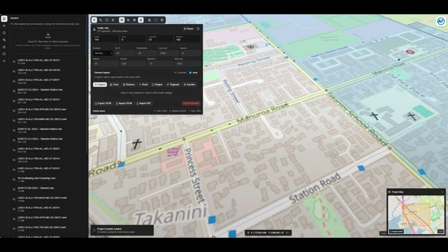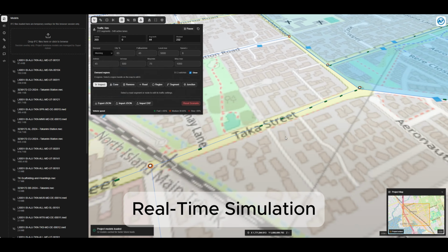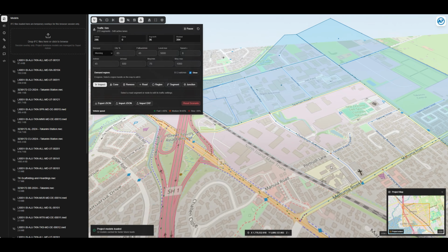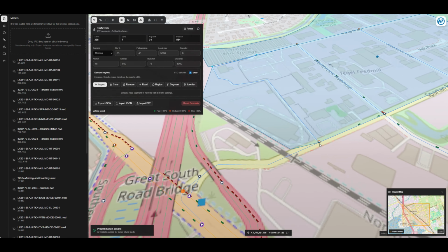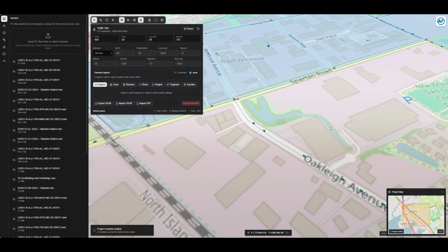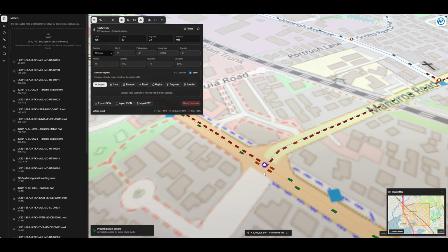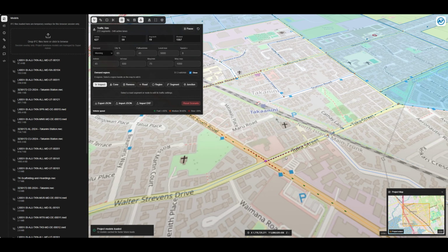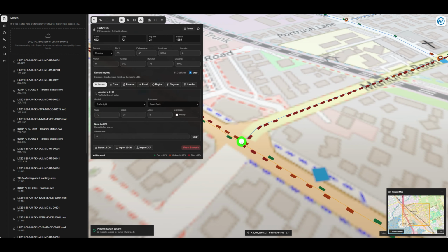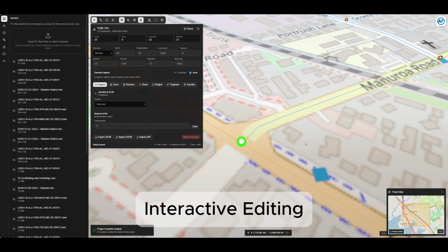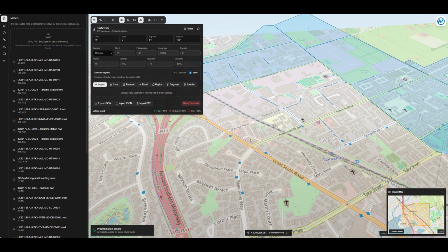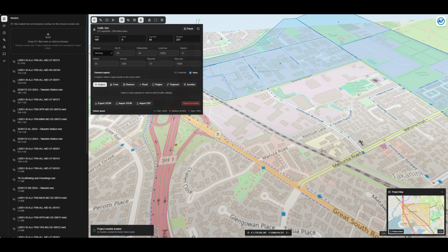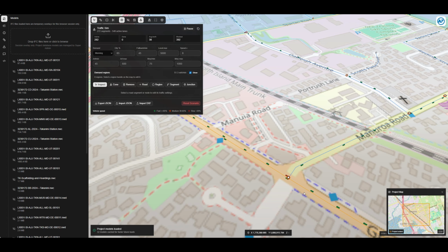The tool runs interactive and is dynamic, meaning that we can see real-time results and impacts on traffic based on a color code scheme. So green cars mean cars are moving at the desired speed of the speed limit, orange means that there is some traffic block, and red means that we've got a larger block in the network system. Making changes to the model in real time has a direct effect on the traffic flow and is immediately simulated and resulted. It is a great tool for traffic management planning.